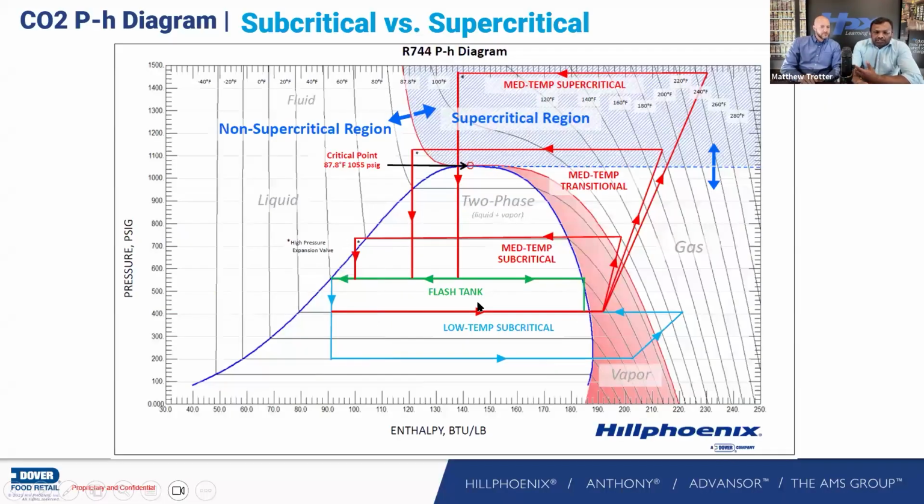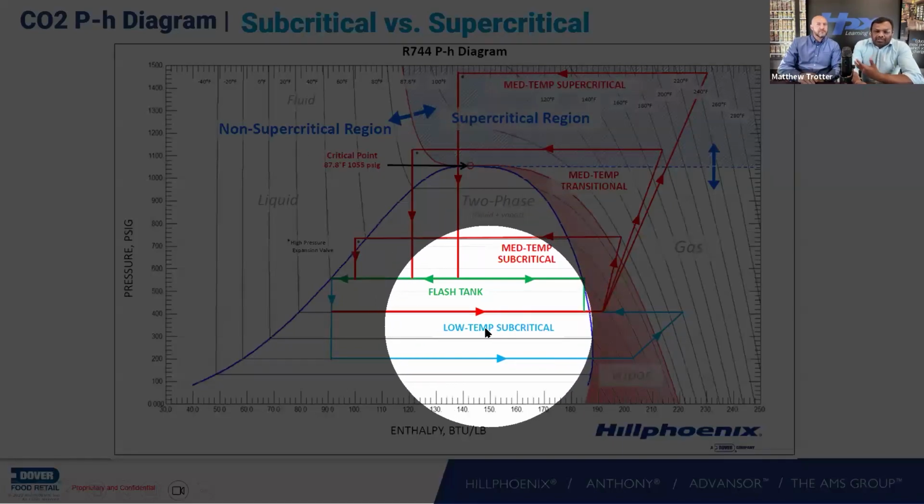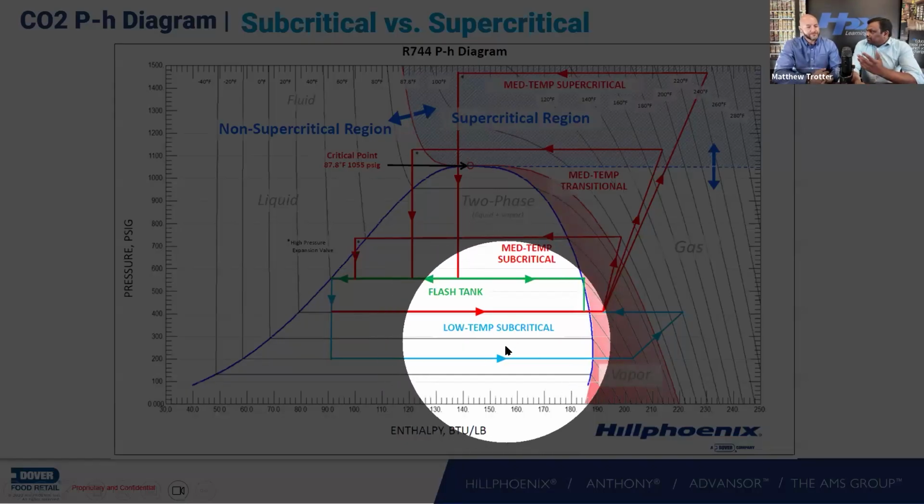To increase the COP of the system by separating the flash gas. So that's the reason we use 4 different pressures. You separate the flash gas and then process the flash gas through medium temp compressors or parallel compressors to improve the COP of the system.